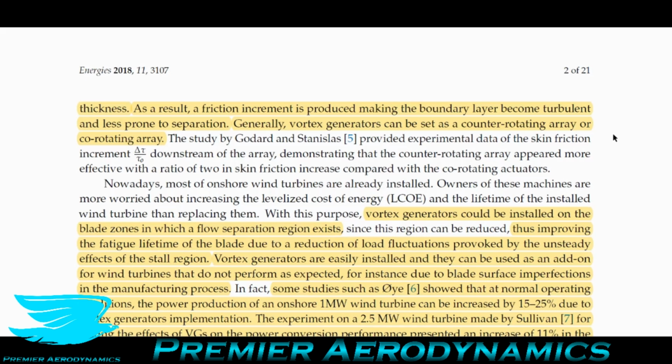Another thing that most people don't talk about is that vortex generators can change the induced drag of the wing. And the reason why they do that is because they change the circulation around the wing. I'm not going to get into that because that was actually a big part of my PhD, and as I mentioned, it's a 4-year project, so I can't really cover much of that in 5 minutes. I'll probably do something else on that later. But they can change the induced drag of a wing based on changing the circulation. I've done some other podcasts talking about circulation as well.